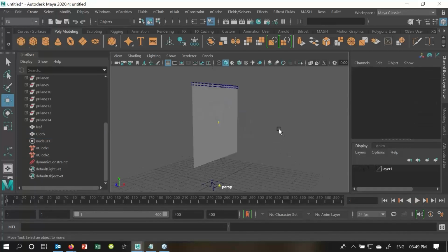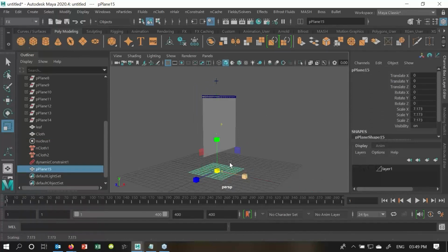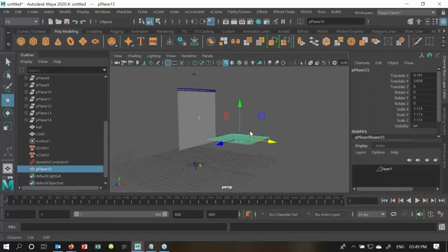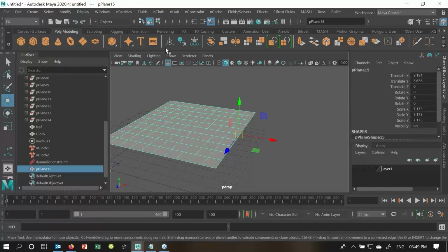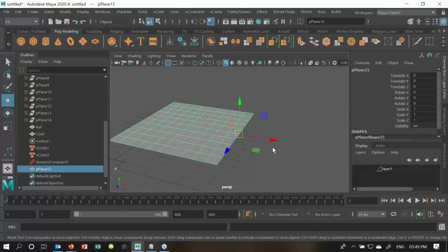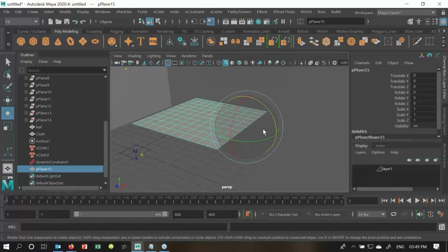Now if I've created a fan in my scene, I'll scale it a little bit and pull it up. D is the shortcut key to move the pivot point. I'll select it and say center pivot point, delete history, freeze transformations, again D, and pull it over here. Now if I want to do the movement on my rotate Z, right?